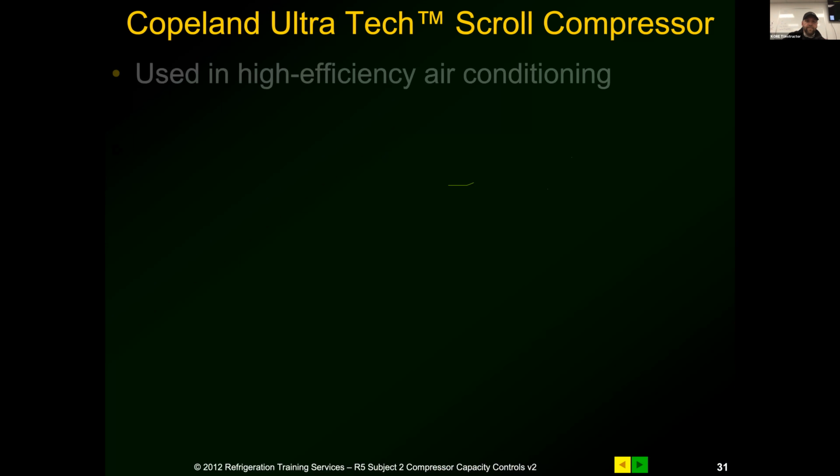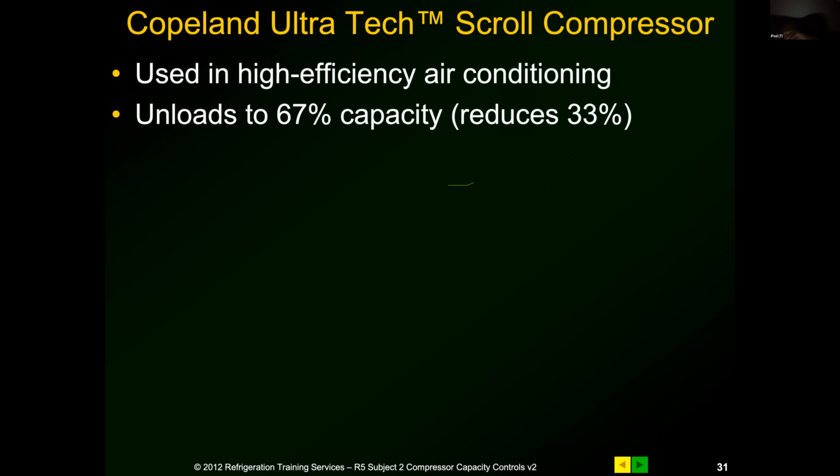So any questions on demand cooling? Hey, can anybody remember? I couldn't remember and I didn't have time to find it. What temperature does demand cooling kick in at? Does anybody know for sure? 250 degrees. Is it 250? The demand cooling starts injecting liquid? Yeah, I think it's 250 degrees.